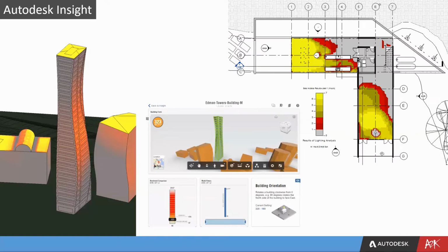And alongside your typical data that you can get out of those feasibility models, such as the areas and the functions as we saw in those previous examples, we can also start calculating things like the building performance. So here we can see some examples whereby we've got some solar radiation analysis occurring around the envelope of the building, which can be useful for working out obviously which facade sides are getting the most impact from the sun, so that you can address that through facade fixtures and so forth. Or it could be optimizing the positioning of things like solar panels to obviously optimize their power generation.